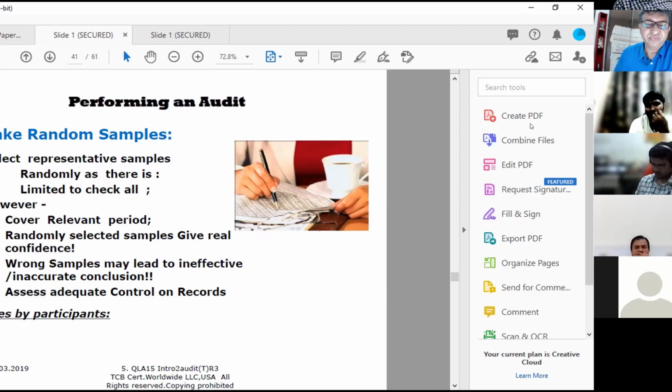I'll take samples. I'll take two welders. Okay, can I see this welder is welding? What is his qualification? Whether it is in accordance with the requirement. I will go to, okay, how do you finally test it? How do you hydro test the system? So take the hydro test report that this is what you have already done. I'm not witnessing, that's different from inspection. I will check whether you have a process that these are done and whether it is hydro tested in accordance with the requirement. It is supposed to be done in 15 bar and you have not done in 15 bars. So I'm not going to ask, show me the test now, you do it in front of me.